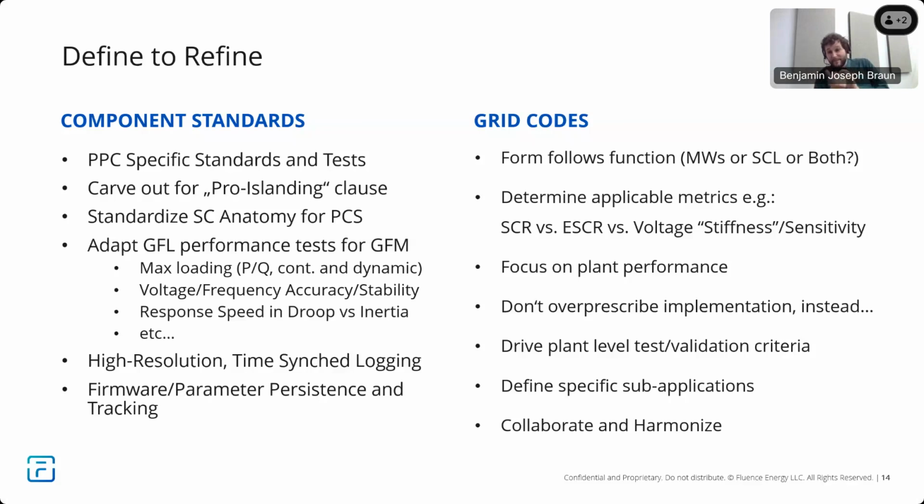If you're an isolated system where it's not just about the stability of the voltage, but really coming down to the nuts and bolts of, can this battery trip my protection settings, then you're totally away from short circuit ratio, and you're just looking at, again, the SCL that the UK used, or in our isolated island projects in the Azores or on Madeira.